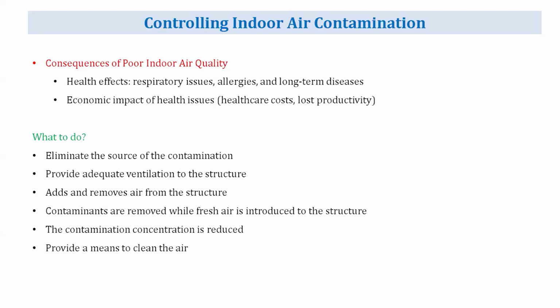So what to do? Simply, we identify and eliminate the source of contamination, provide adequate ventilation, and add or remove air contamination with dilution by fresh air. So these are the few things which we can do.